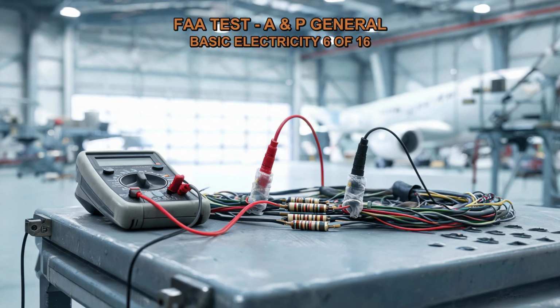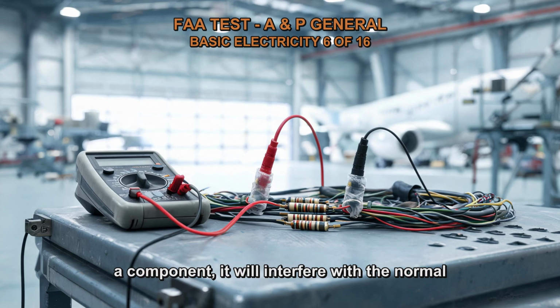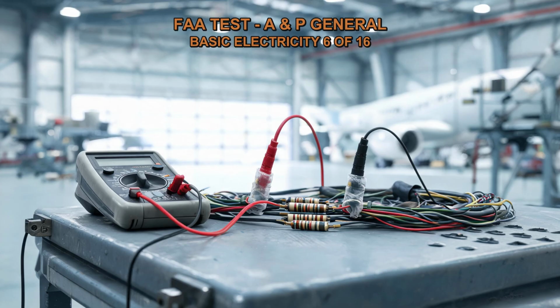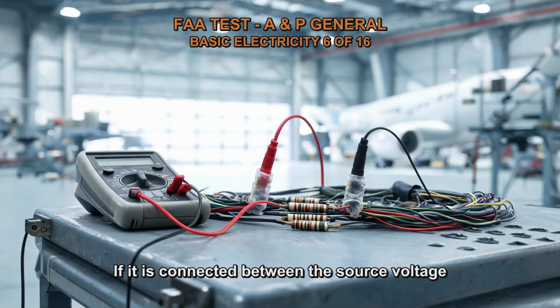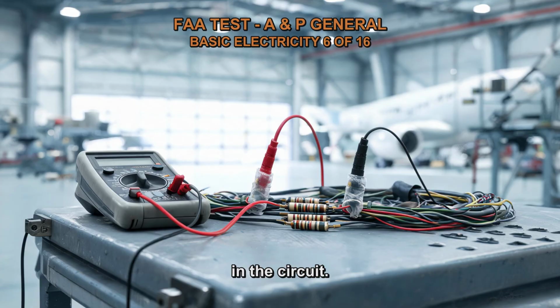potential, usually ground. If a voltmeter is connected in series with a component, it will interfere with the normal operation of the circuit and may cause inaccurate readings. If it is connected between the source voltage and the load, it will not provide a specific measurement of voltage across any particular component in the circuit.